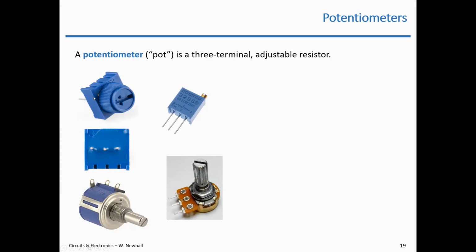So you turn this knob and it adjusts resistors. I'll show you this inside this device. You turn this screw and it adjusts the resistance. The same thing with these knobs. This looks like a volume knob here, with the knob taken off. So here's what a potentiometer schematic symbol is. And so what you'll see, it's a 3-terminal device. It has A, B, and W as terminals. And it has a value, RP. That's going to be a value in ohms. And I'll show you what that means.